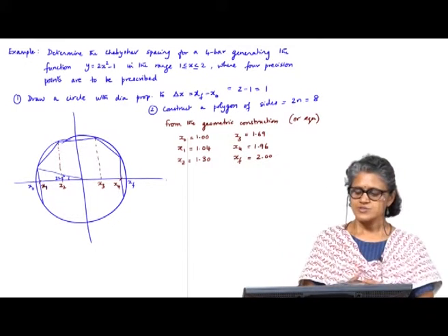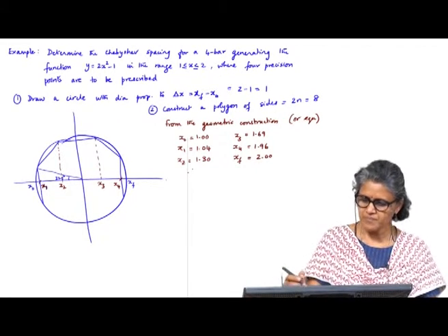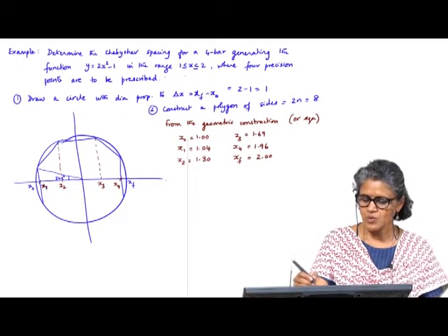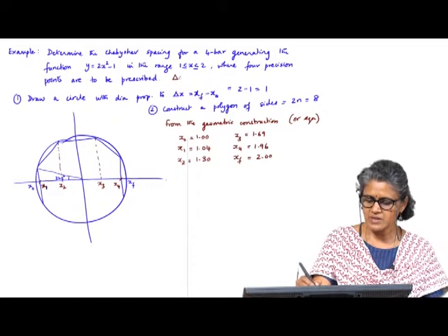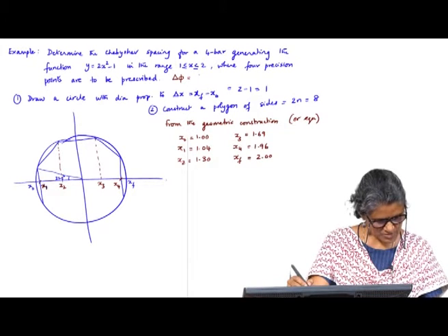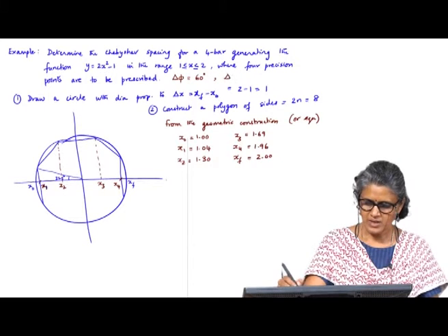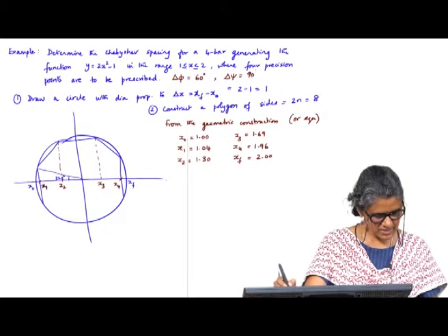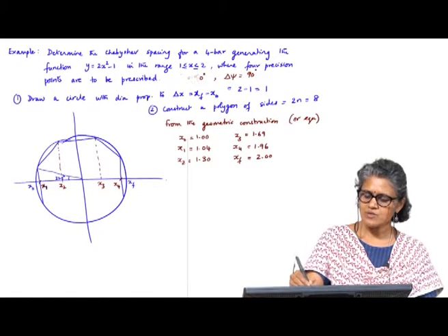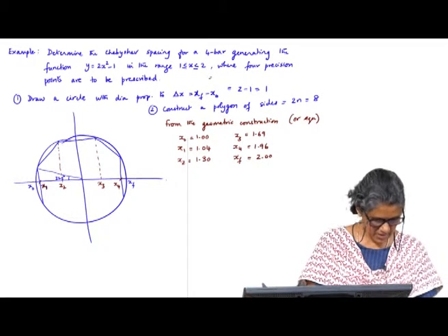Okay. So once I have the values for x, there's one more thing I need to be given. What would be the range of rotation for the 4 bar? So I am given delta phi, the input angle, and delta psi is 90 degrees. So the first part is finding the precision points for this relationship.